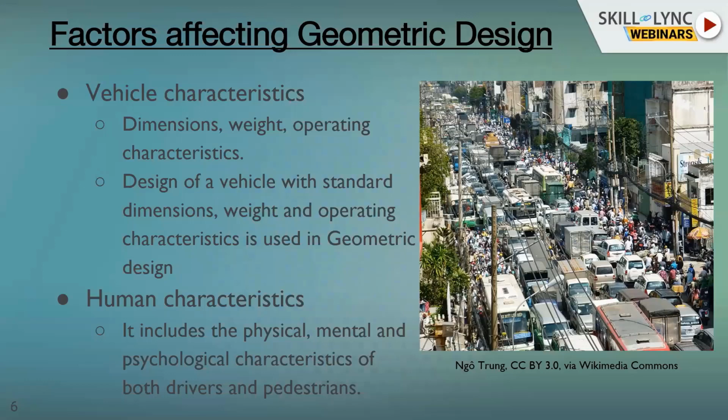That too means a signalized intersection, or you want to have an at-grade intersection at some places, but normally definitely the road width at this location is not sufficient. So you can see there are so many vehicles that this road width cannot accommodate those vehicles. This is the primary reason.